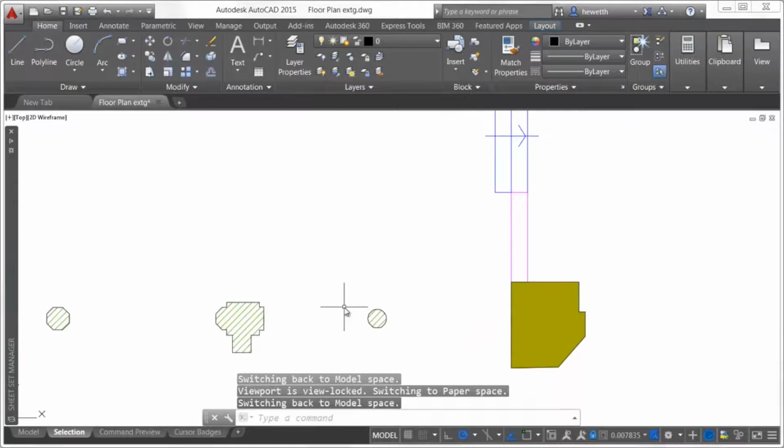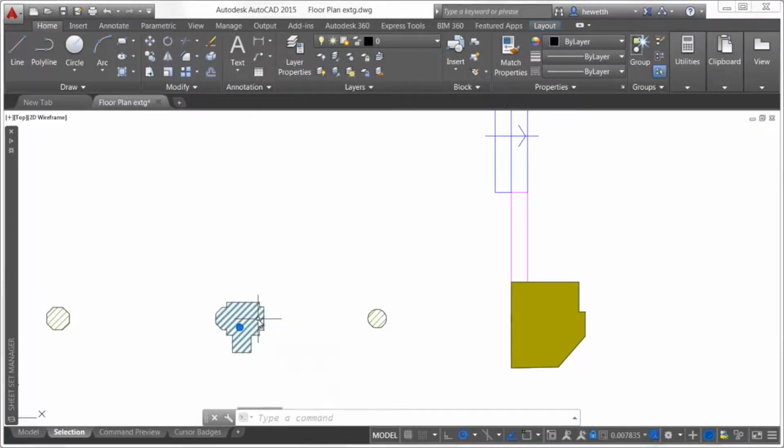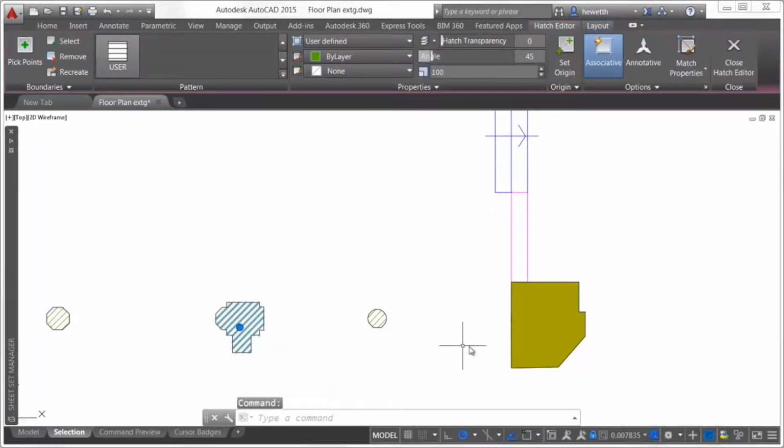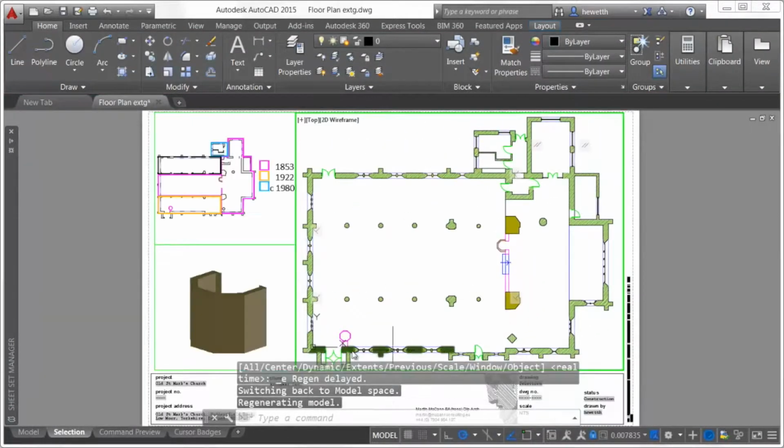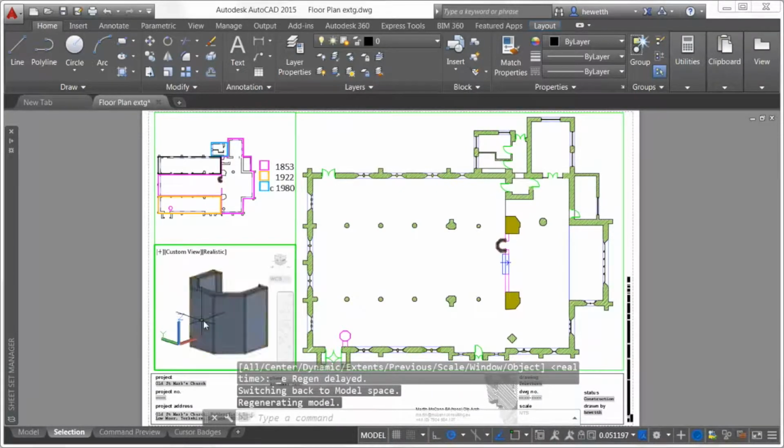When you select objects using any method, AutoCAD 2015 offers modern and clear feedback. As you pass the cursor over an object in the drawing, the line geometry appears thicker and darker or lighter depending on the background color. If hardware acceleration is turned on, selecting an object changes its color and it remains thickened to clearly identify it as part of the selection set. Similar visual enhancements help you clearly identify when faces, such as solid hatches or 3D solids, are selected.